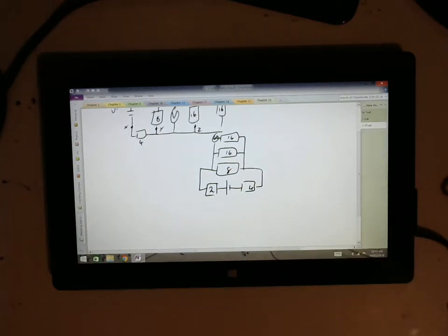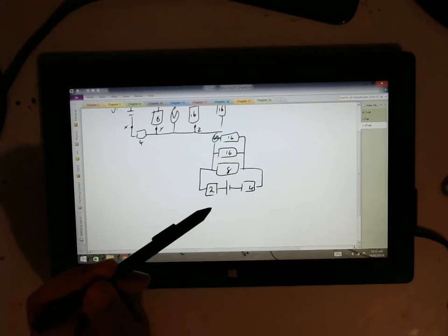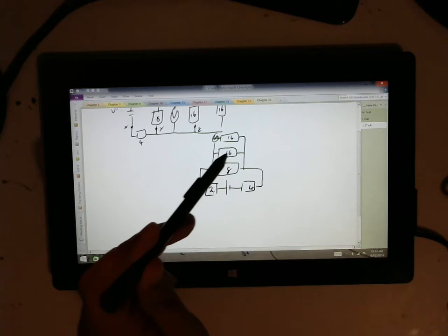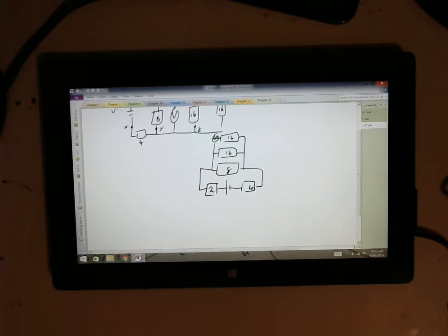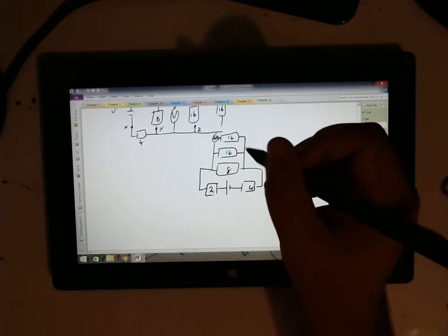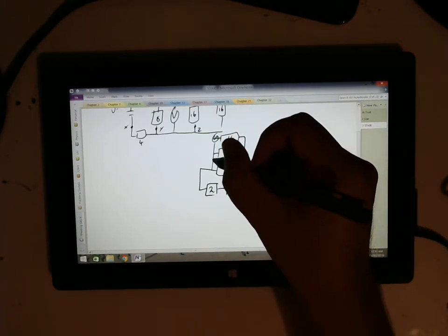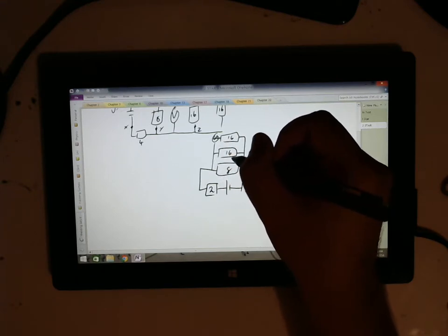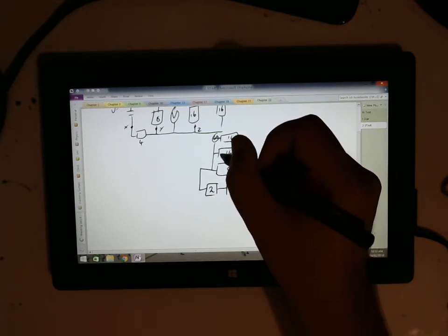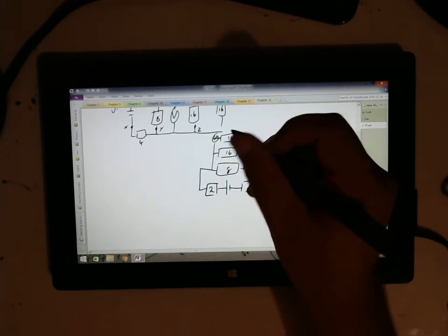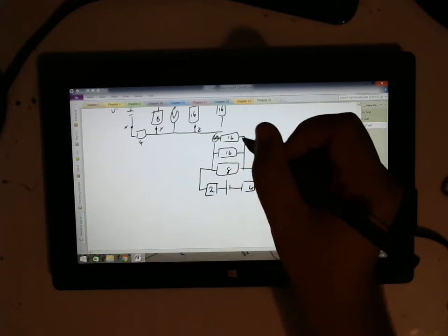Now I like this diagram a bit better, because I was thinking about resistance equivalences, and I could see that these 3 things are in parallel with each other, and once I work out that big chunk, I've got these 2 bits in series with it. And we also want that voltmeter, and the voltmeter is going between the 8 and the 16 on the picture, and what it's really doing is working out the voltage before and after this huge section of parallel circuitry that's going on here.